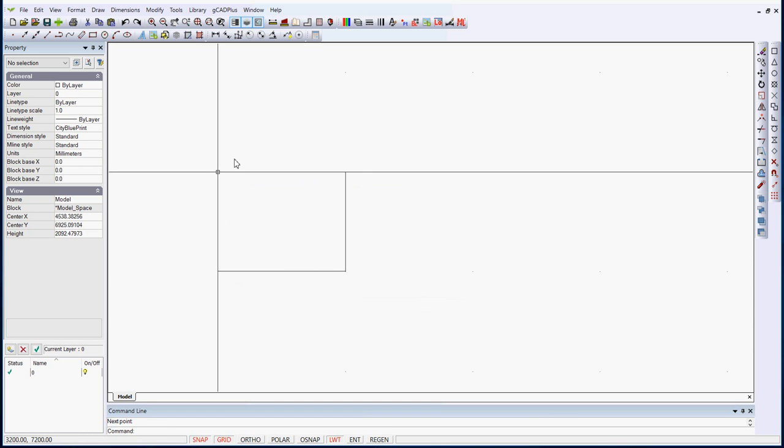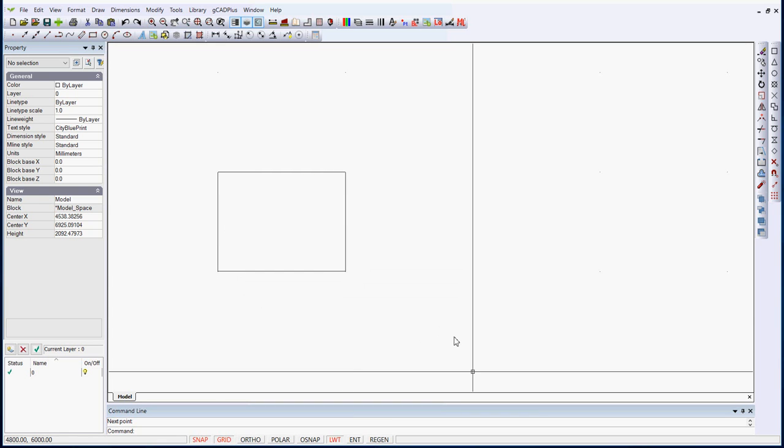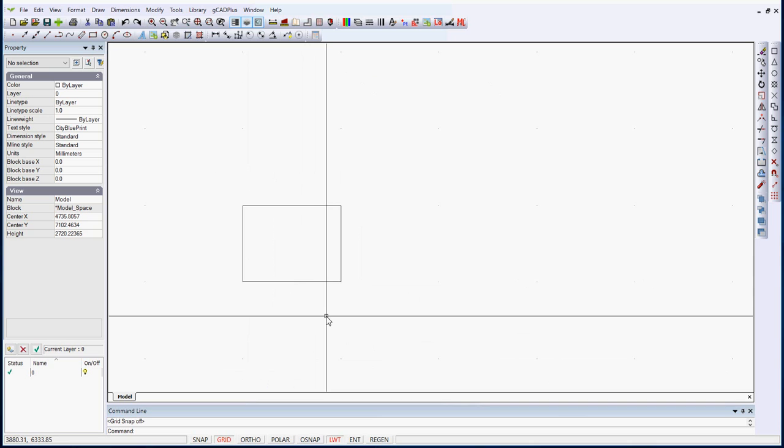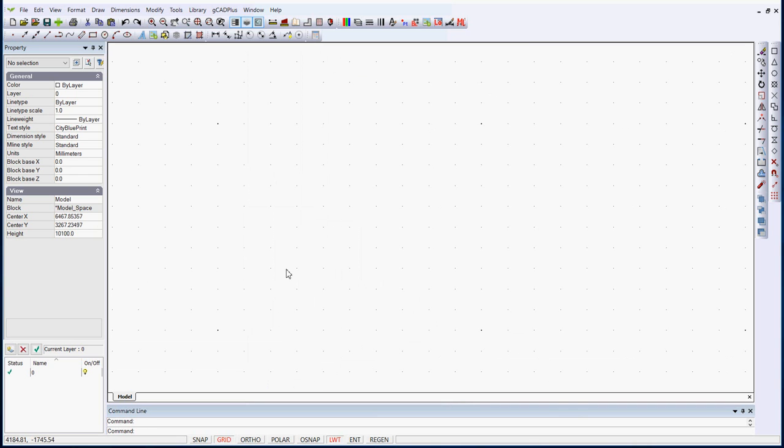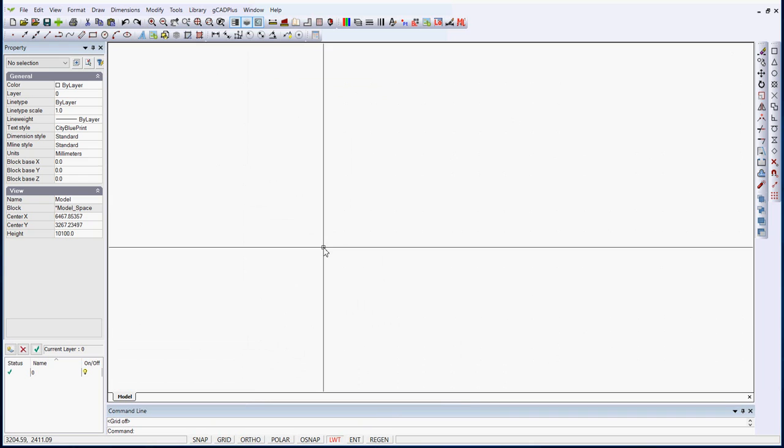We haven't worried about its positioning on the screen. We've just clicked and things lock in. You'll see as you're trying to move around how the cursor is anchored, and we need to turn Snap off. So there's the first method, using the line command to construct our paving brick. I'll now turn off the grid and we'll draw the paving brick using another method.